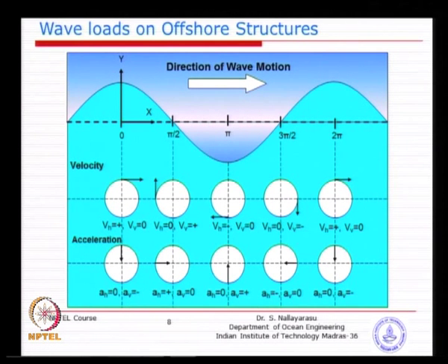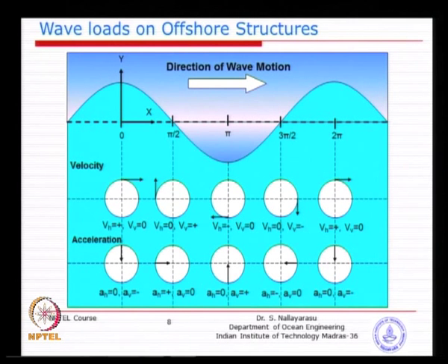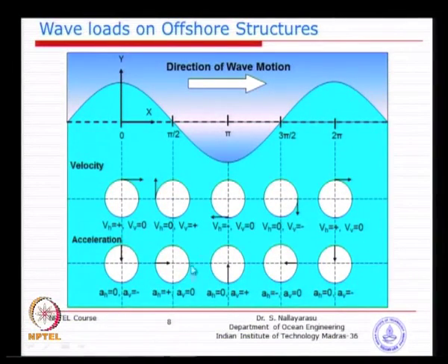That is something you need to remember, because when you are computing wave force, you will see that wave force can be found at each time step, and then you need to find where the maximum wave force happens. This is a dynamic force that changes with time, because the wave is not static but progressively moving. That is why you need to find at what instant of time the structure will be subjected to maximum force, which we do not know a priori. So we have to look at various time steps along the wave propagation.